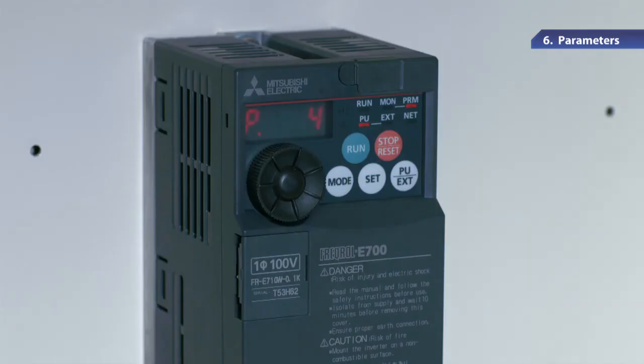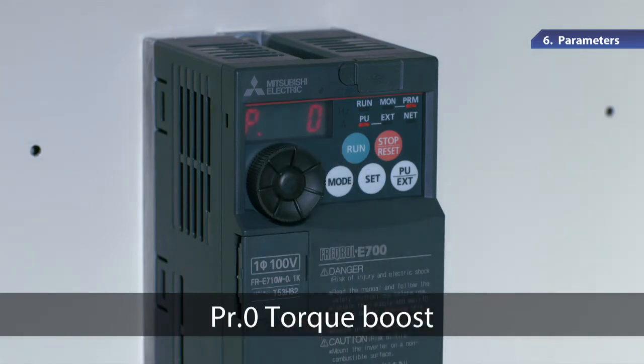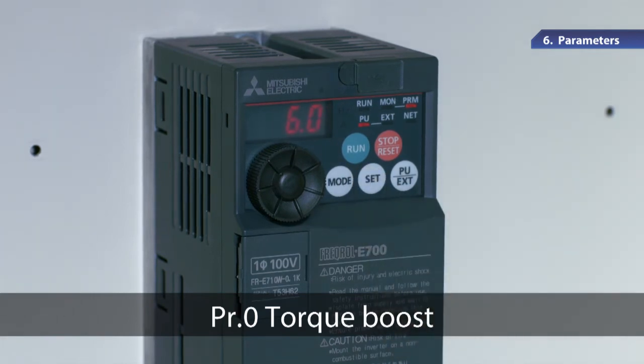Imagine you are about to start pedaling a bicycle with heavy luggage on the back. You need a strong force for the bicycle to start and move forward until it is in a stable motion, right? Parameter 0 has a function called torque boost. Motor torque in the low frequency range can be adjusted according to the load to increase the starting motor torque.